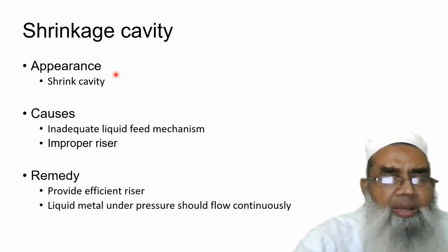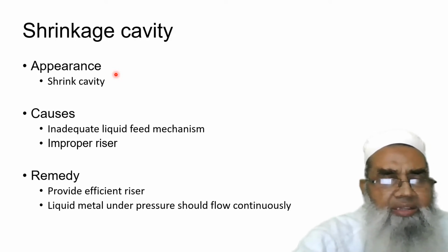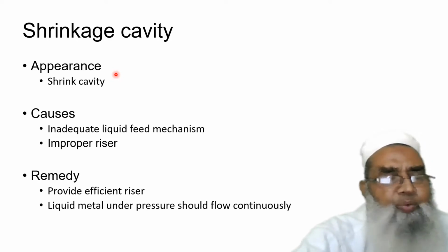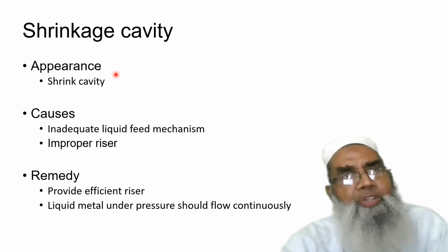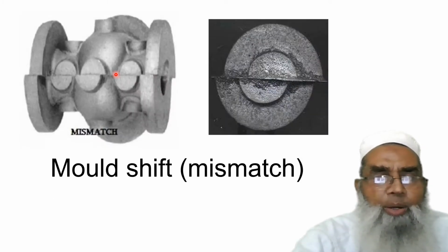Therefore by having a proper, efficient riser such that the liquid metal under pressure flows continuously during solidification, only then can we avoid the shrinkage cavity.